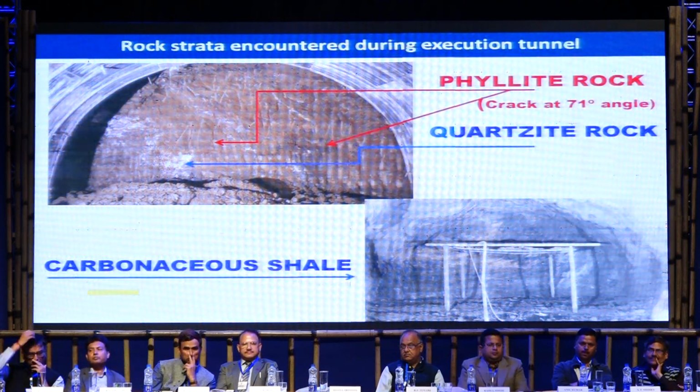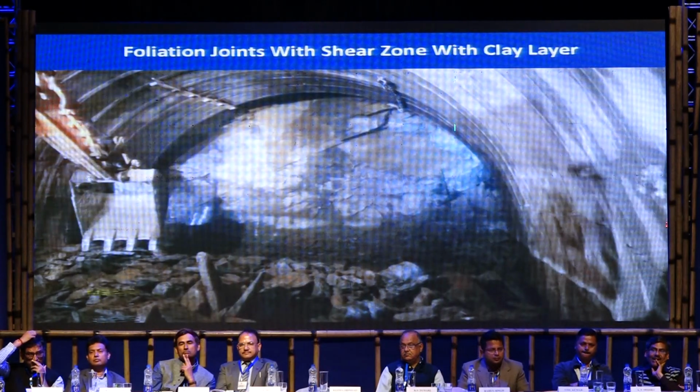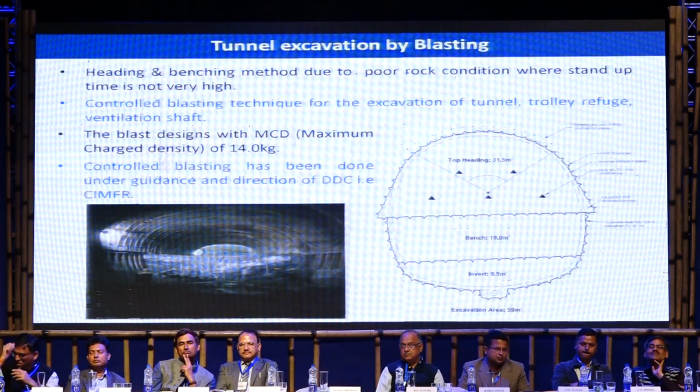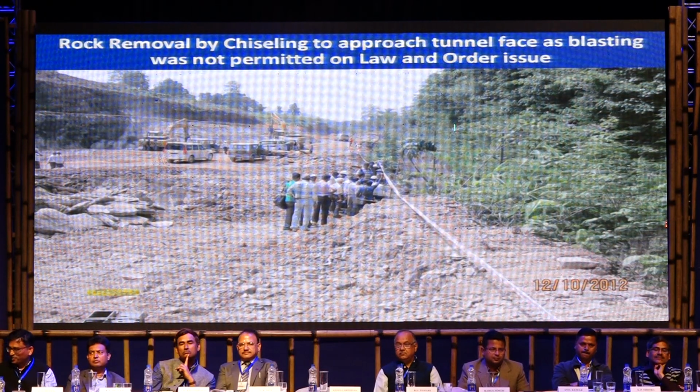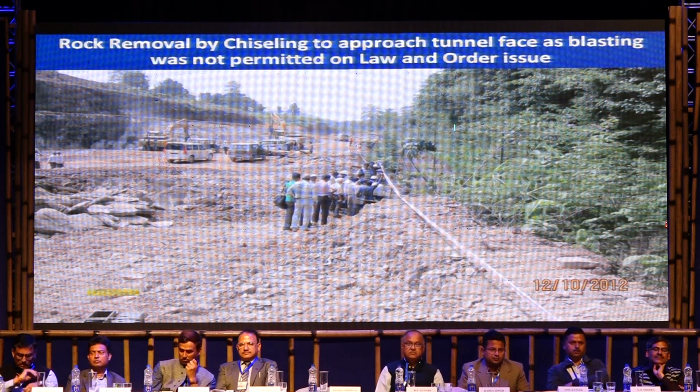So these are the fallen rocks there, unstable rock. Heading and benching is used because we reduce the quantum of blasting potential, the blasting amplitude. This is the approach portion. We cut it here not by blasting, because we are not allowed by the state authority. It is by the chiseling method that we remove a huge rock mass.